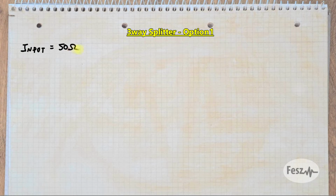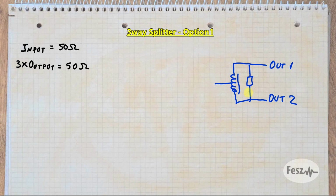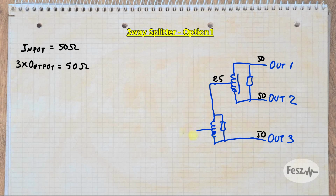Using these principles, you should be able to design a 0-degree splitter with any number of outputs and with any port impedance. To test things out, let's look at the problem of creating a three-way splitter. For this task, I found two main ways to do it. To make understanding this a bit easier, let's impose that all ports are the same impedance, say 50 ohms. Starting from the output, the easiest way to make a three-way splitter is to first combine two of the outputs into a single line. This will be half impedance, so 25 ohms, and then we need another transformer, but this time an imbalanced one. The input of this will be 16.6 ohms. To finish things off, we need an impedance matching transformer to go back up to 50. So this has all ports at 50 ohms.